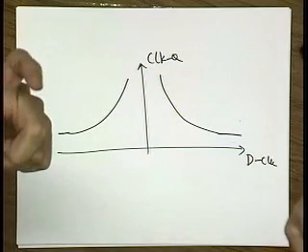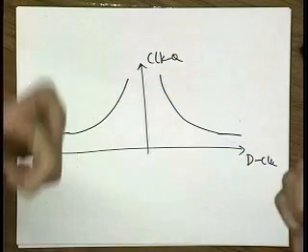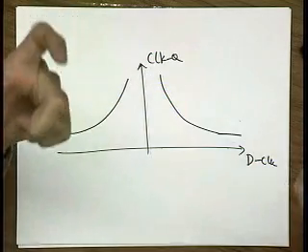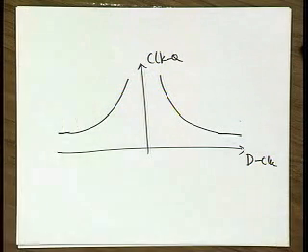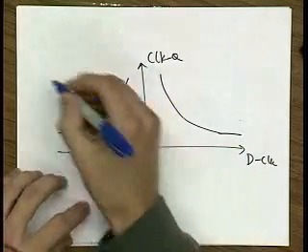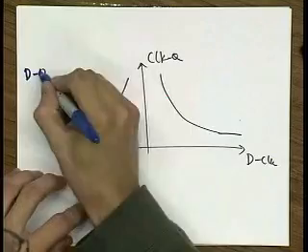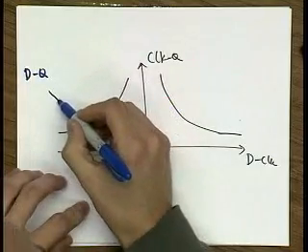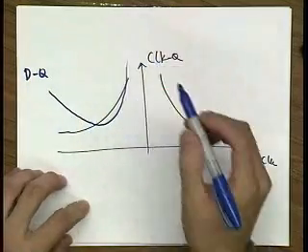What this means is how much cycle time you steal from your logic design, right? Because you have clock to Q, you have logic delay, you have setup time of the next stage. So if you assume that you have the same circuit in the previous and the next stage, it's interesting to look at the sum of clock to Q and setup. Setup is defined by this axis, and if I plot data to Q over here, what I'm going to have is something like this.